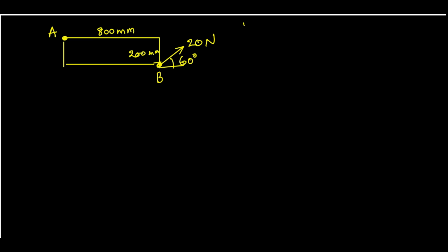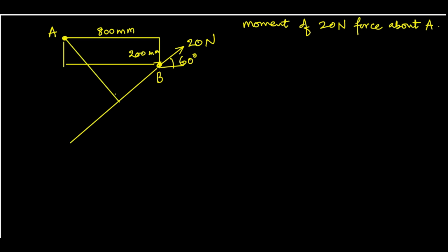You want to find moment of 20 Newton force about A. So now you extend the line like that and drop a perpendicular onto that line.